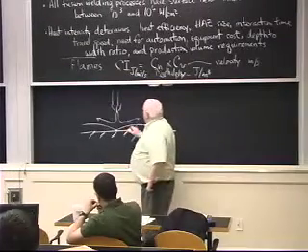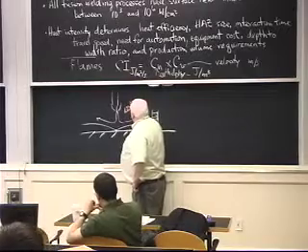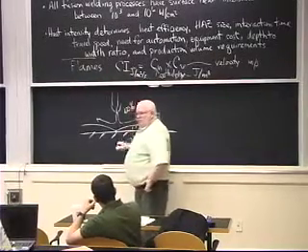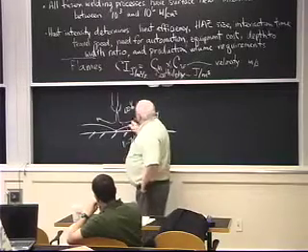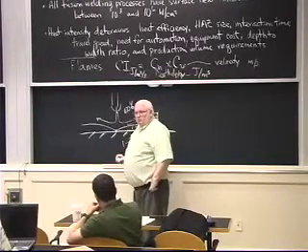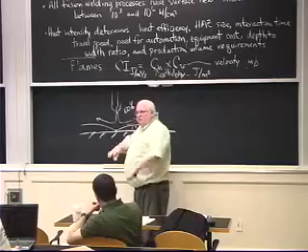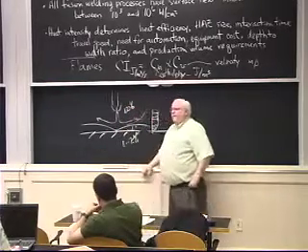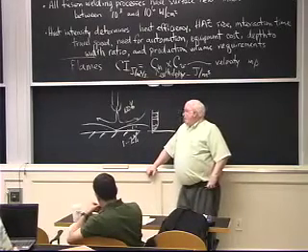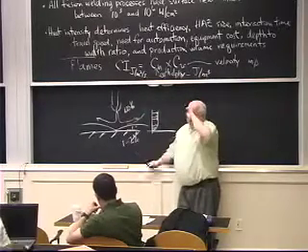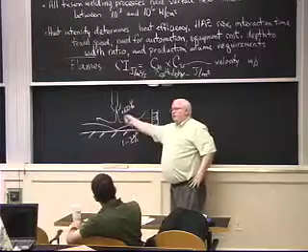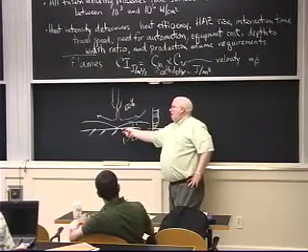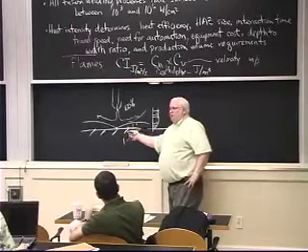And so even though I have 100% of my heat coming out of my nozzle, I only get about 1 to 2% of my heat actually transferred into my solid or my liquid condensed phase. And most of it just goes to heating up the welder. If this guy's an oxy-acetylene welder, it just heats up his environment and makes him sweat. Does this happen with all the gases or only with the air? It happens with any gas, whether it's air or anything else. If you have it hitting a solid surface and then turning the corners, you'll form boundary layers.